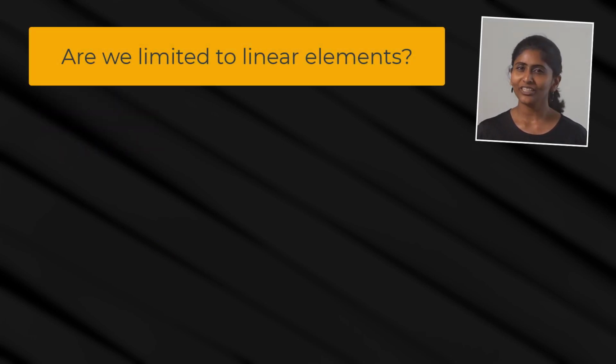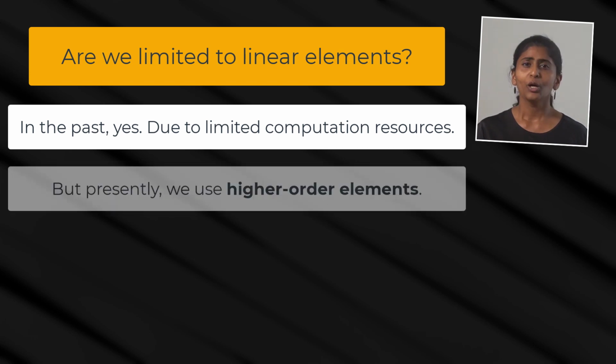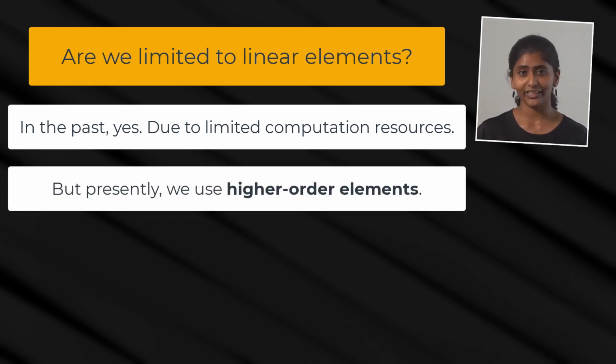Are we limited to linear elements though? In the past, users of finite element analyses were in fact often limited to using linear elements due to lack of sufficient computational power. However, due to advancements in numerical methods and computational resources, we presently use higher order elements without having to worry about the computational costs.